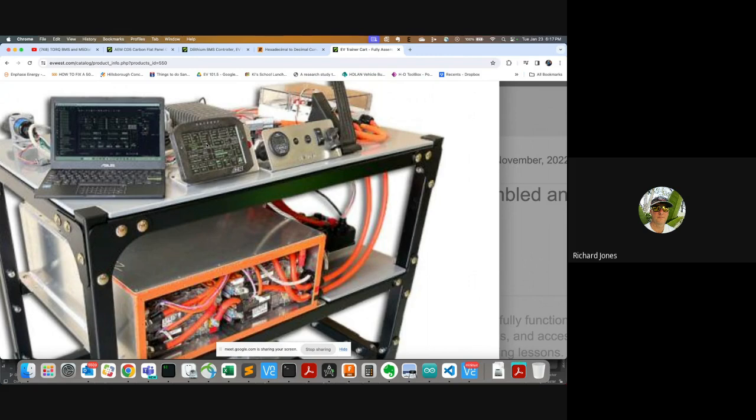So you have a CAN message, which has up to 8 bytes in it. And then there's a description called a DBC file, a database file, which uses the terminology of a signal. A signal might say the first 2 bytes of message number 123 is cell 1's voltage, and it's interpreted this way. And you have a minimum value and a maximum value.